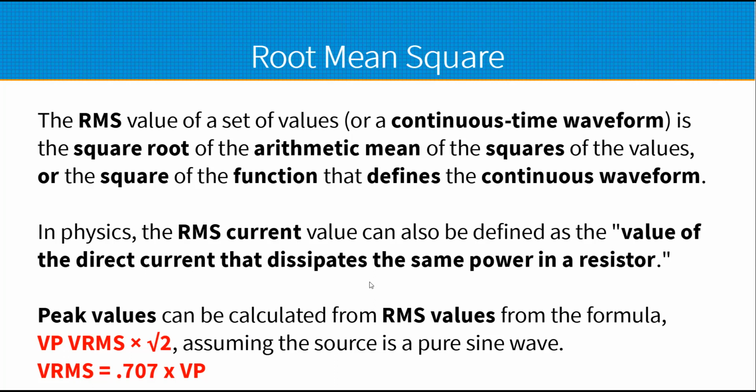It turns out it can get complicated if there's any DC component to it where there's an offset. It turns out to be the square root of the AC RMS squared plus the square of the DC part to get that result. I'd never dealt with that, but it does make sense.